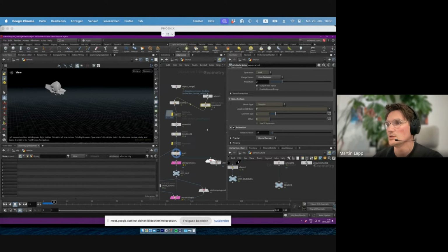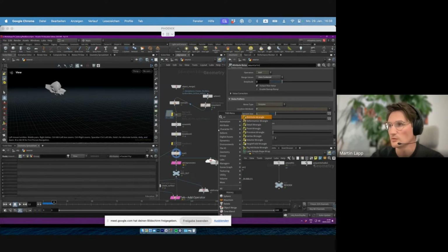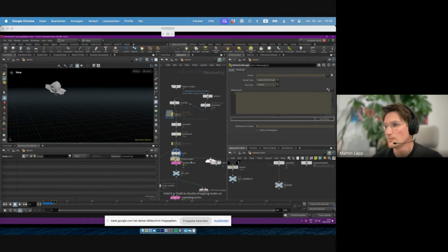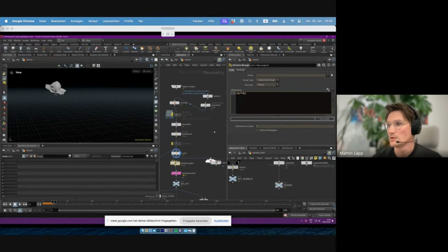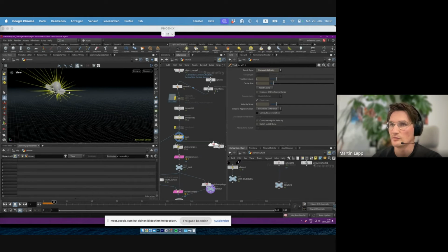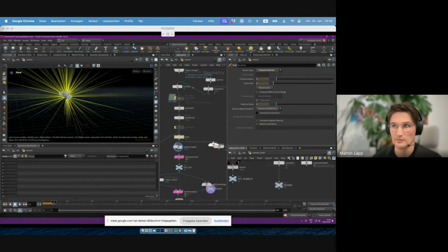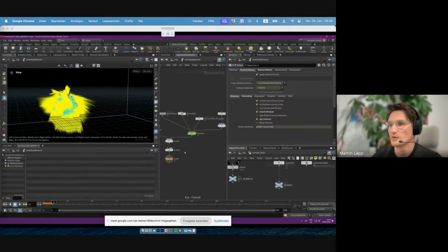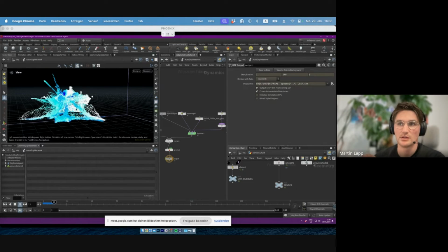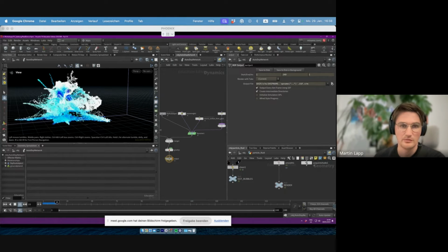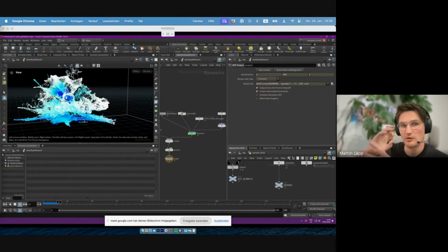Let's actually make this, I can also push that in a wrangle. So that trail, I'm just going to say my V attribute, I'm multiplying this by, say, 5. So now my velocities go from this size to this size, right? So if I now feed this into my simulation, then it will be quite splashy. So this is the first, and we are just using initial velocities, right? We're just changing the velocity of our source.